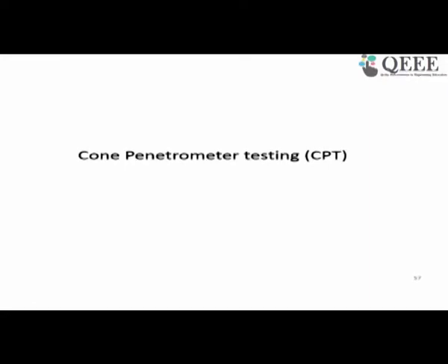Changing or lifting the drill rod and changing to the sampler is always difficult and cumbersome. So why not go by some automatic method where all the data are recorded directly? So there is a method called cone penetration testing or cone penetrometer testing.